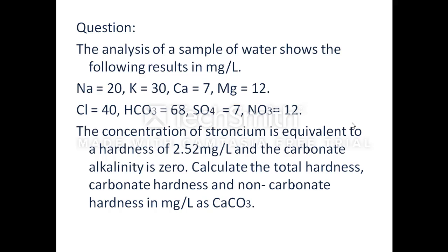Here the concentration of sodium, potassium, magnesium, calcium, chlorine, HCO3, SO4 and NO3 is given. And the concentration of strontium is not given, but the hardness caused by strontium is given. That's equal to 2.52 mg per liter. And the carbonate alkalinity is equal to 0. And we have to find out the total hardness of water, carbonate hardness, and non-carbonate hardness in terms of calcium carbonate. Now solving the question,